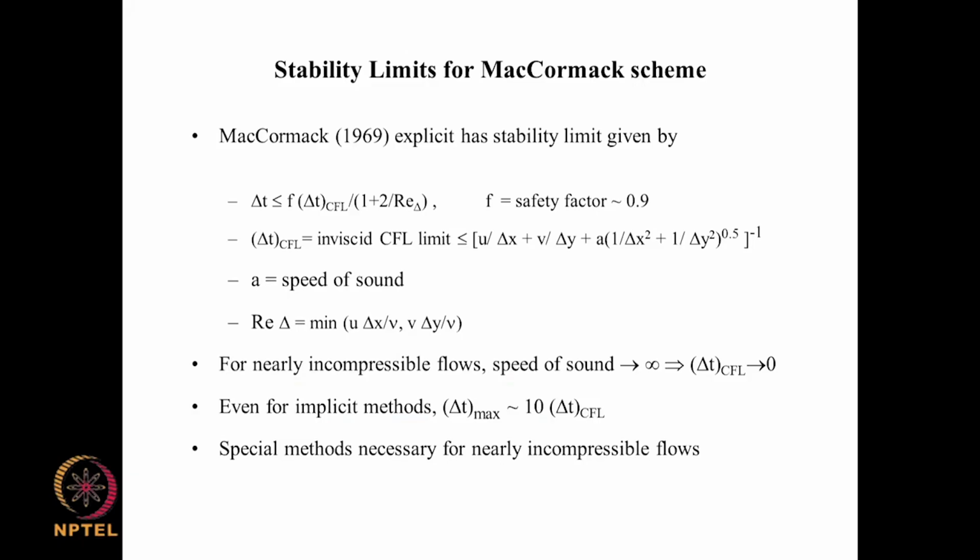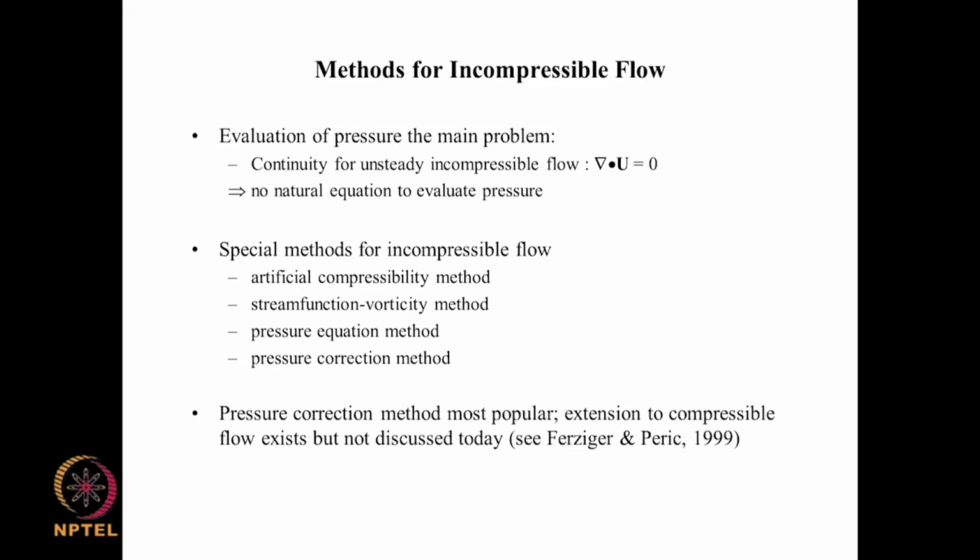So, if density is not there, then the linkage between the continuity equation and the momentum equations through pressure, density and the equation of state is gone, and in such a case we will not be able to use the density based methods that we have seen in compressible flows. We also saw that there are special methods that have been developed: the artificial compressibility method, the stream function vorticity method and the pressure equation method.